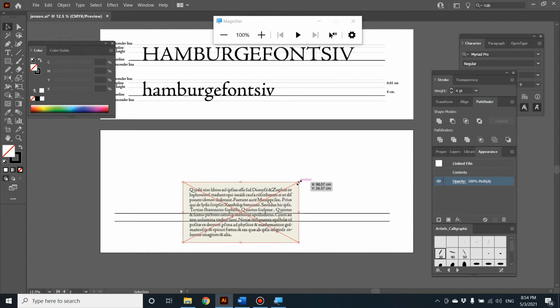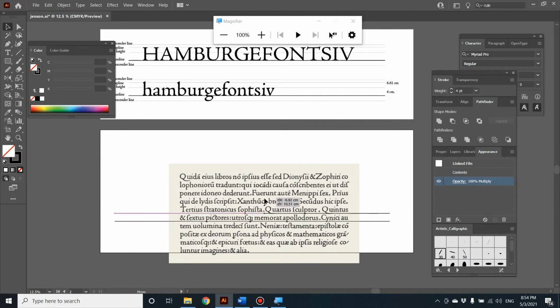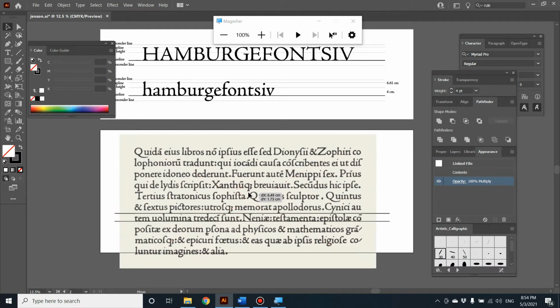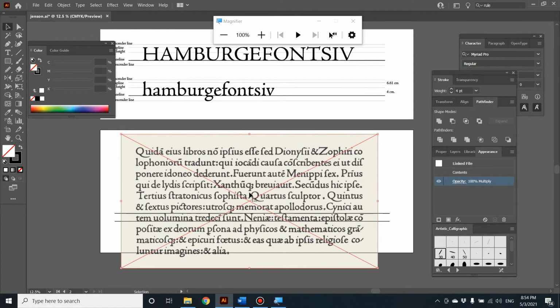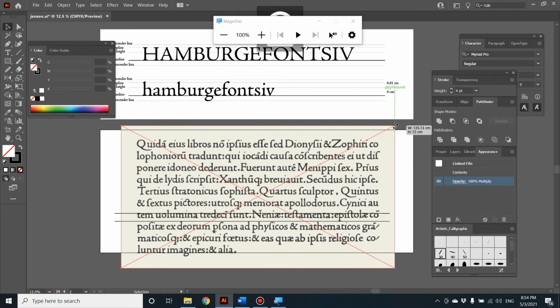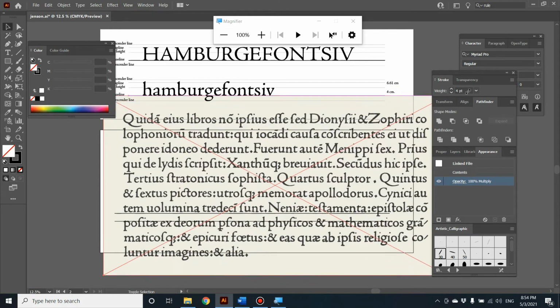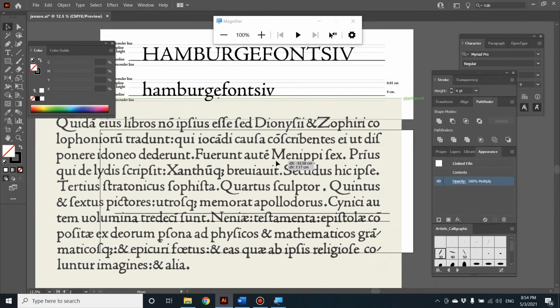The next thing is to enlarge this picture, make it bigger. And what is the x height exactly? X height is the distance from the baseline to the mean line, where the lowercase x sits. It is used to define the other characters as a whole, so you don't have to draw each character randomly.